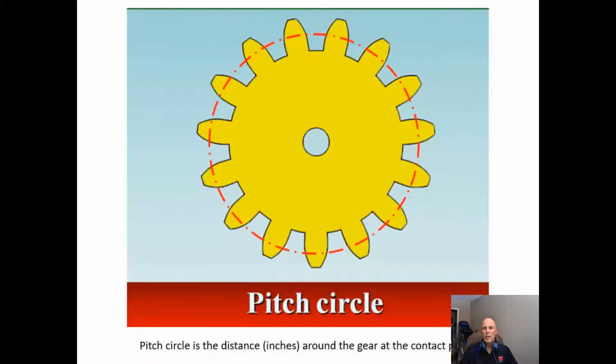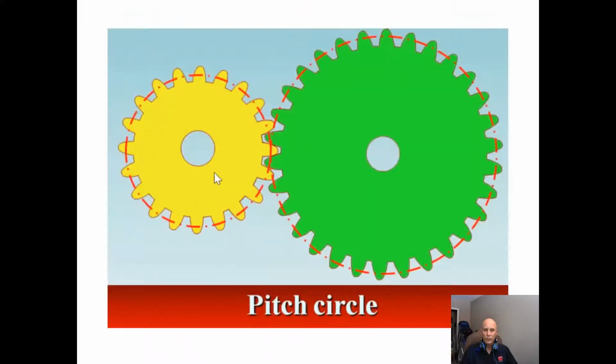Now we can increase this gear size by 10 times, which let's just say then we would have, I don't know, 40 teeth around there. The diametrical pitch will still have to be 4. Otherwise, the teeth will just not mesh. So again, when we take a look at a pitch circle, here we have 2 gears of different sizes, but our diametrical pitch will be identical to both.